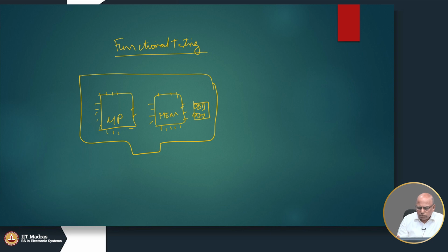Then what do you do? What do you suspect? Do you suspect that the microprocessor is bad, the memory is bad? So, this method where we plug everything into the PCB, assuming that all of these are good components, is risky, right. So, a better approach is to first test each of these components. We can test the microprocessor separately, we can test the memory separately, right.